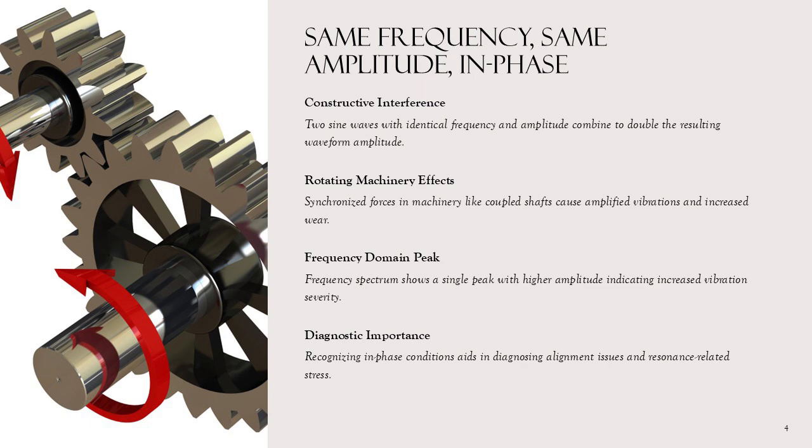In the frequency domain, the spectrum displays a single peak at the shared frequency, but with significantly higher amplitude, indicating increased vibration severity. This scenario is important for analysts because it demonstrates how synchronized forces can amplify vibration levels, potentially accelerating wear or causing structural fatigue. Recognizing in-phase conditions helps in diagnosing alignment issues or resonance phenomena, where components vibrate together harmoniously, leading to elevated stress